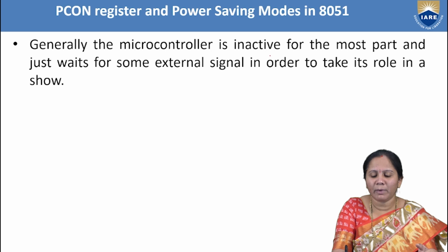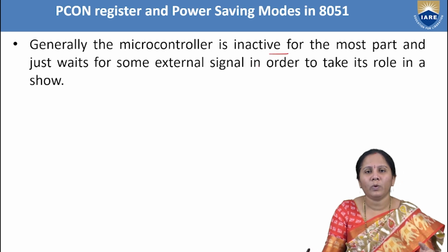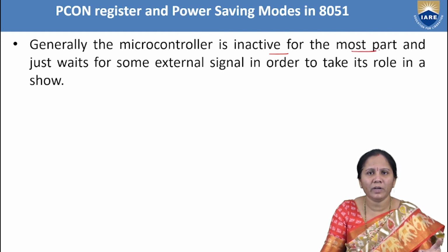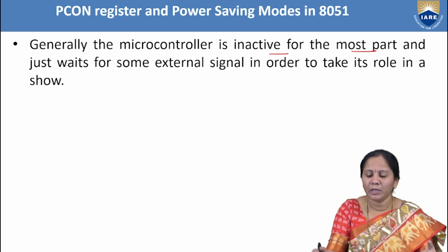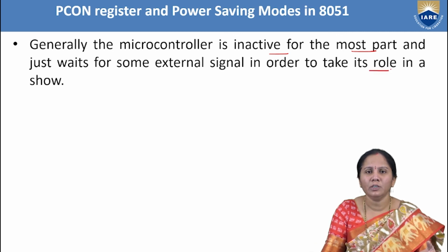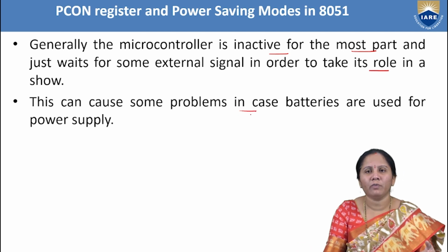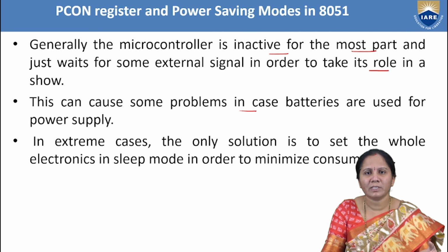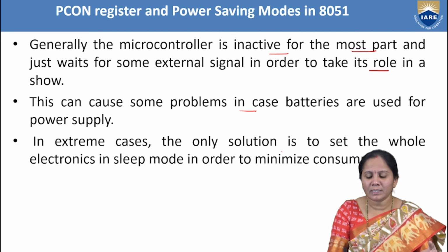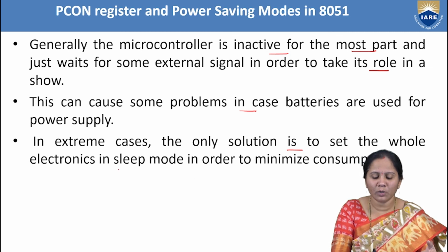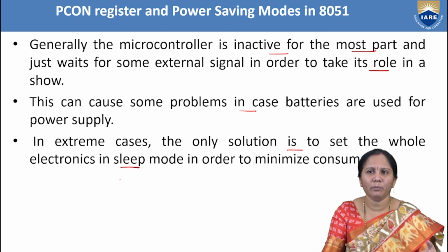Why is this PCON register used? Generally the microcontroller is inactive for the most part, and it just has to wait for some external signals in order to take its role in the show. This can cause some problems in the case of batteries that are used for power supply. So in these cases, what is the solution? We have to set the whole electronics into sleep mode in order to minimize the power consumption.